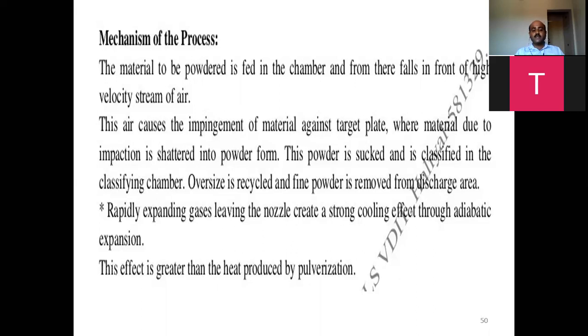Rapidly expanding gases leaving the nozzle create a strong cooling effect due to adiabatic expansion. This effect is greater than the heat produced by the pulverization. This is the mechanism of this process.